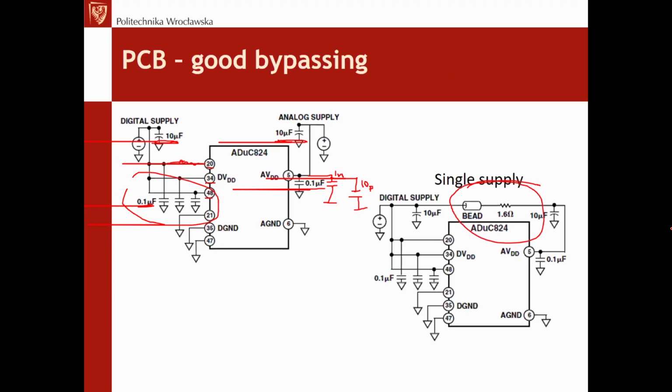The analog, as you know, requires a much cleaner power supply line. And because we have a good grounding, the cleaning can be done most effectively. So we can use RC filters. The RC filter is this one, the resistor and capacitor making the filter. Actually we have a pi filter: capacitor, resistor, capacitor.